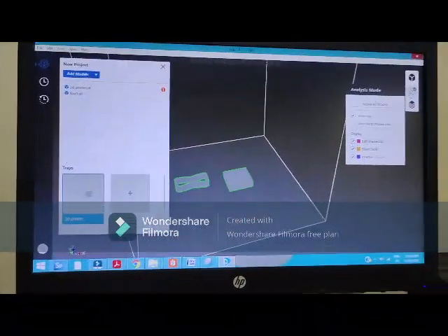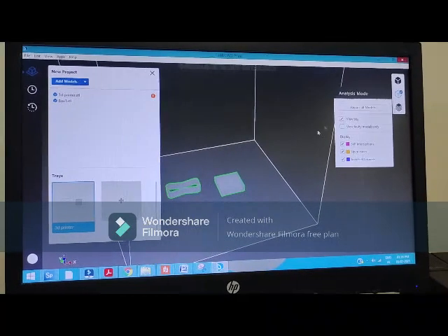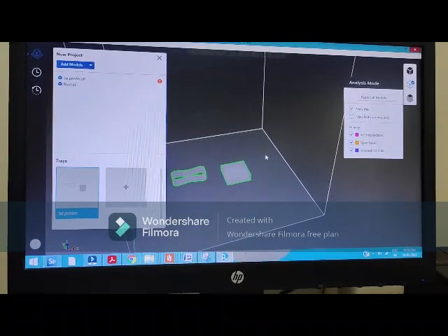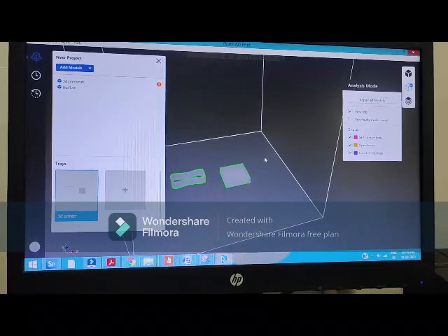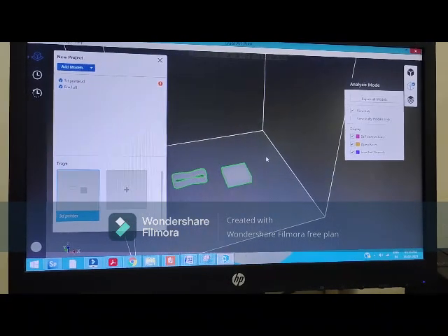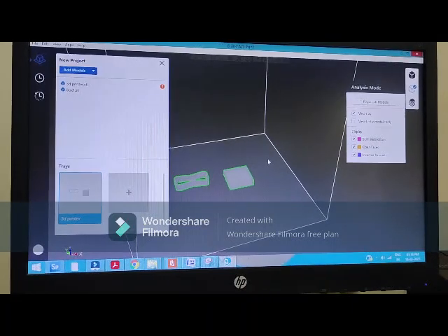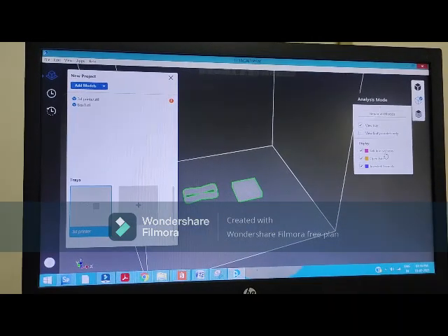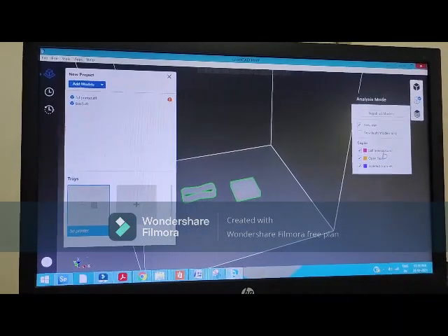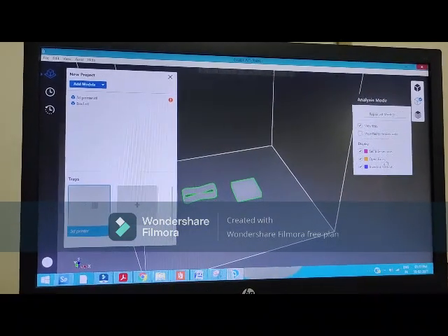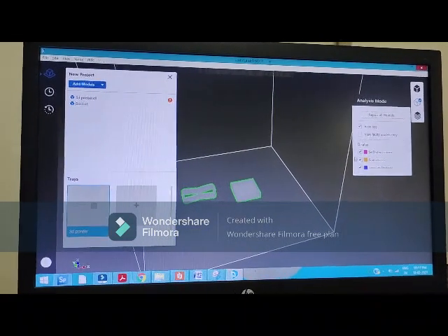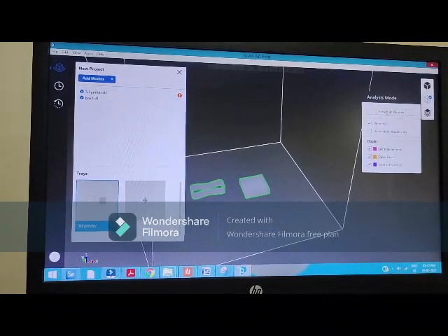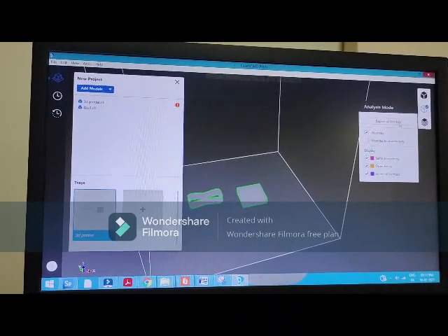Here we can go and check this option. Suppose we had some problem with the geometry. Once we create a geometry, we can have multiple problems there, like open geometry, intersection points. Suppose two points are intersecting, or the boundaries are open. Those are very complex things. You can see here in the display it is giving us self intersection, where the model is itself intersecting, open faces, inverted normals. We are not going deep into this. It is going to check all these things, and if we have some problem, we can go to repair mode. So this is the repair all models option, so we can repair it.